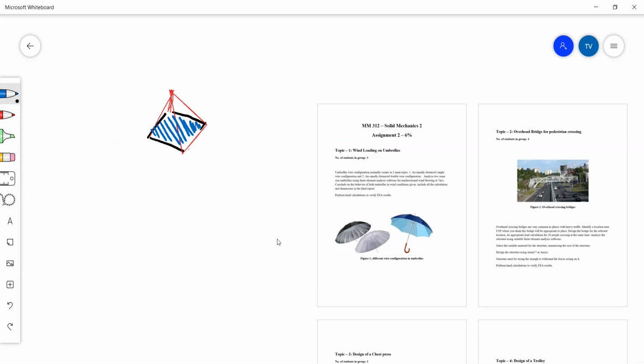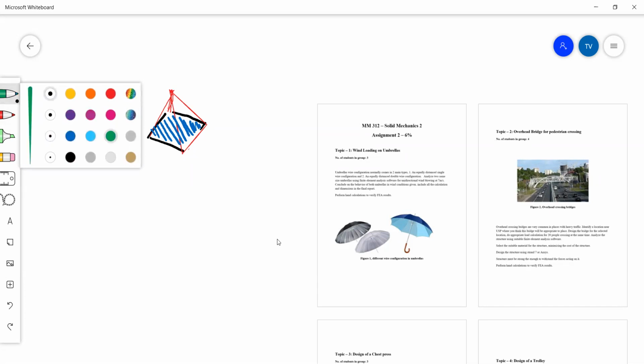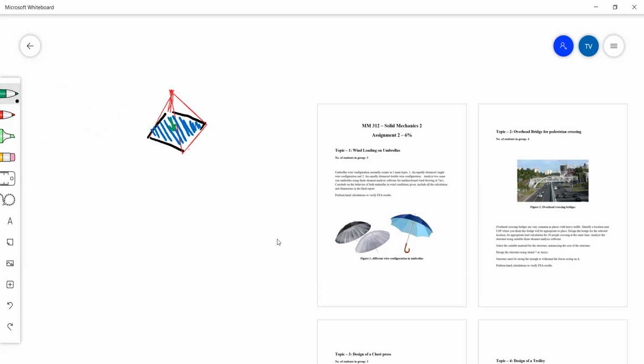Okay, and then we'll apply one force. We'll apply a force here and we'll restrain these, and we'll apply 3 different material properties. We'll have a plate, we'll have beams at the bottom, and then these red ones will be a different beam. Okay, that's the kind of thing we're going to go for, just to demonstrate how you do different material properties.